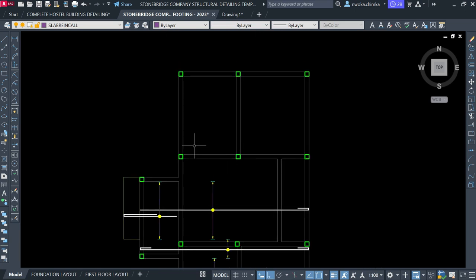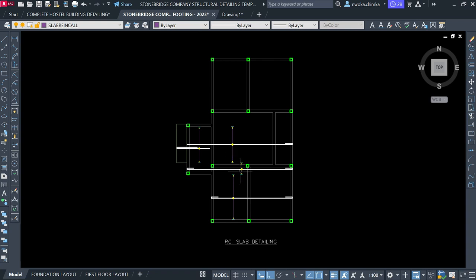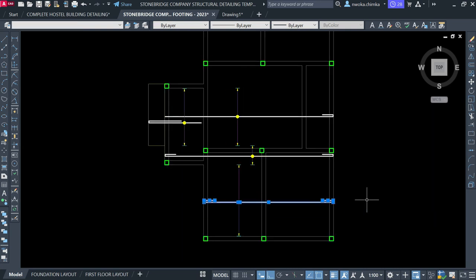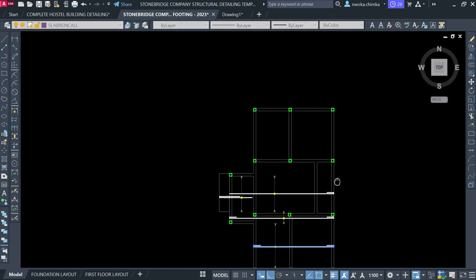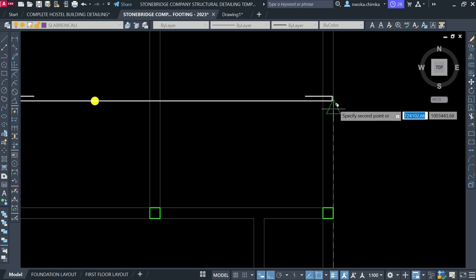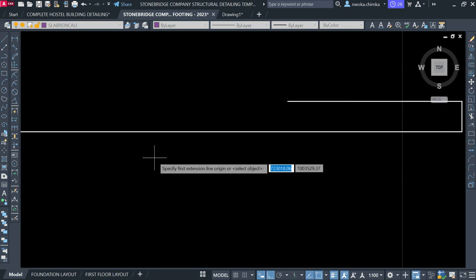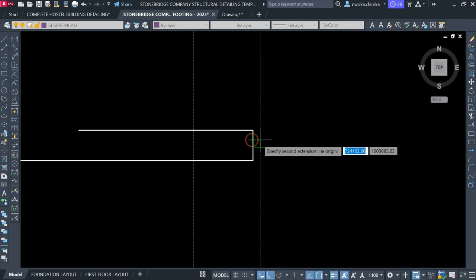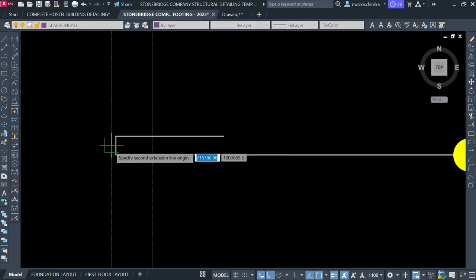So right now, we will begin to do the same thing here. Looking at this place, you can almost see that this shape here is always the same as this shape here, as you can see. So I'll just go ahead and copy this bar here, copy this bar for the face of this beam, and then go and place it here and copy it here. That's fine. Confirm my cover if it is the same, 25. Let me see. Confirm it here. Yes, 25, that's fine. Confirm here too, 25 also, as you can see, that's fine.